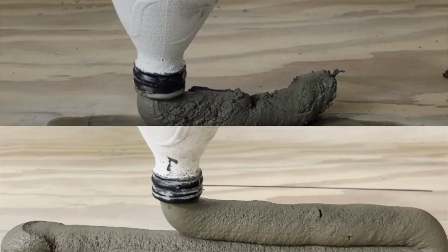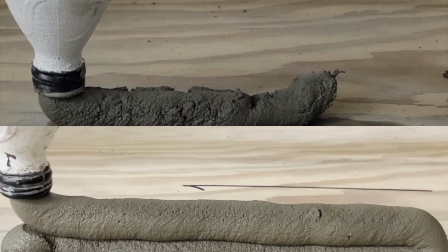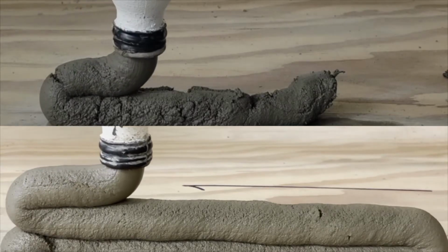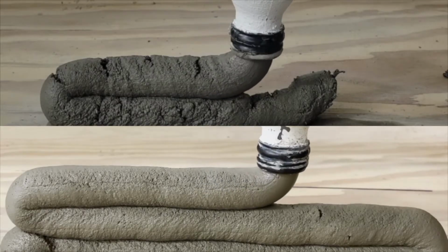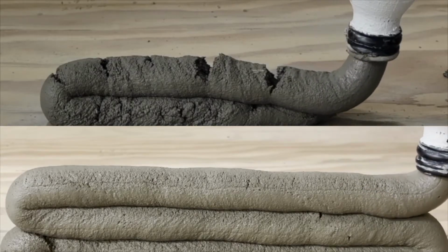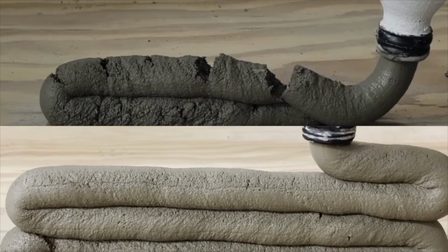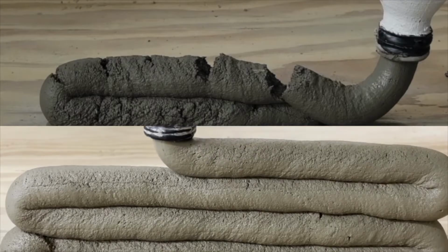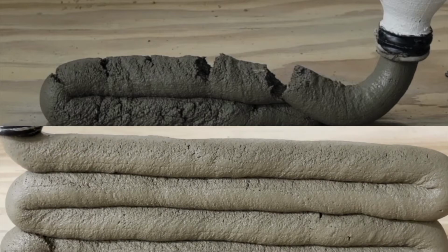Optimizing a mixture proportion to reduce the risk of blockage and to enable continuous flow through the nozzle is a big topic, and it's beyond the scope of this discussion. I may just highlight the importance of the solid particle optimization and its impact on extrudability. The two mixtures that are compared here have the same amount of cementitious material. Even the water content and sand to binder ratio is the same. The main difference between these two mixtures is the aggregate gradation and the packing density. The mixture with the higher packing density showed a much better extrudability in this test.